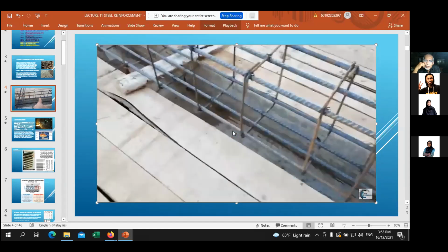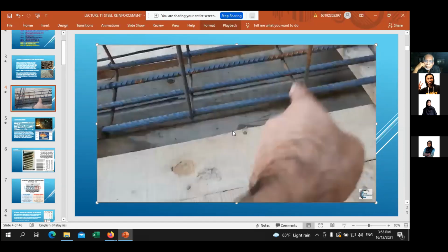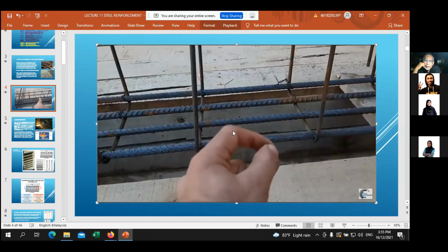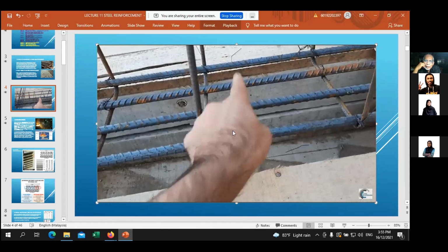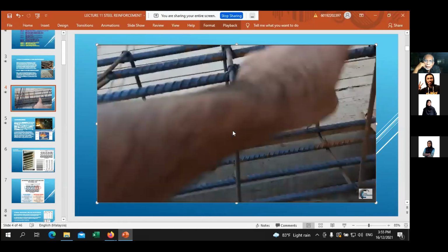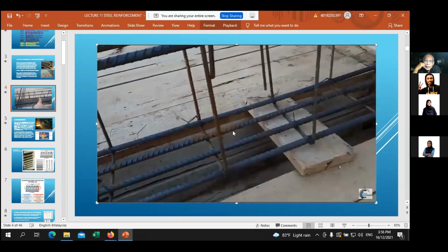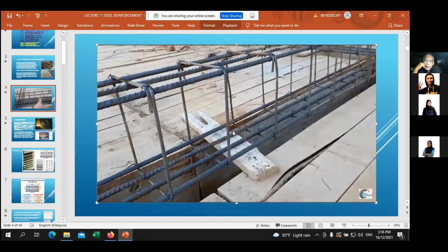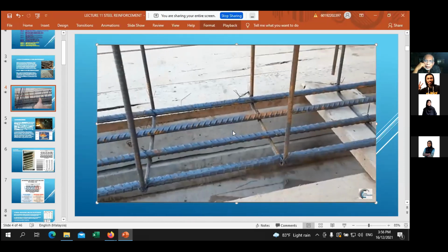Now guys, here in a 3 or 4 story building and top beam, at the mid we should provide the cut piece, because we should increase the strength of beam at the bottom. Because the top bar transfers the load to the bottom, and bottom bars can give the load to the column, so we should provide the extra bars here. But they didn't provide.